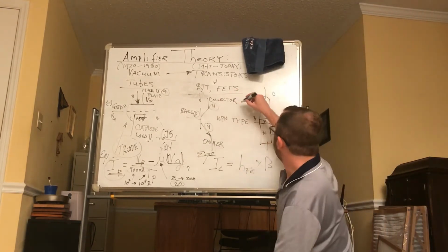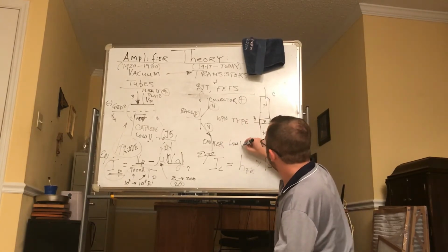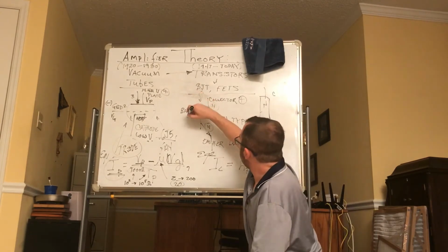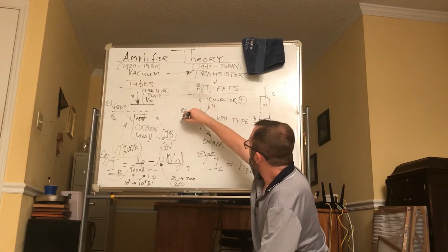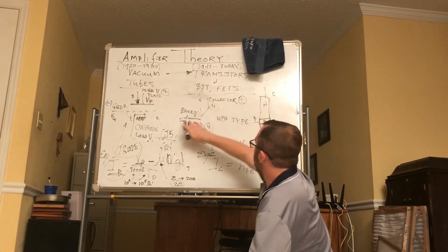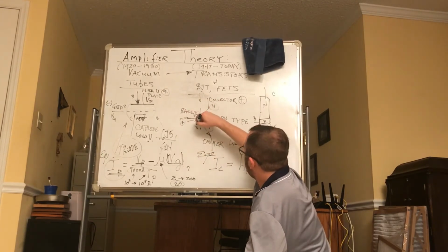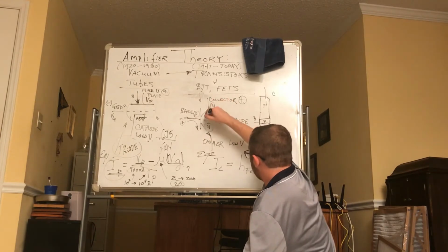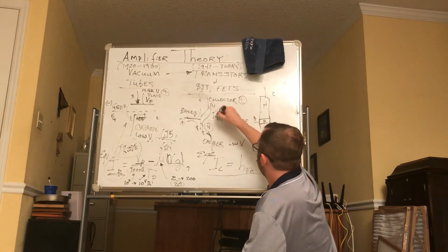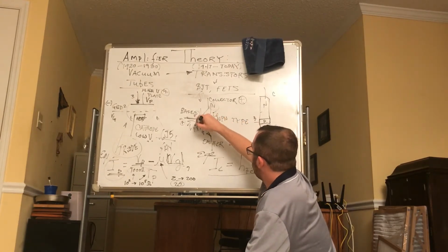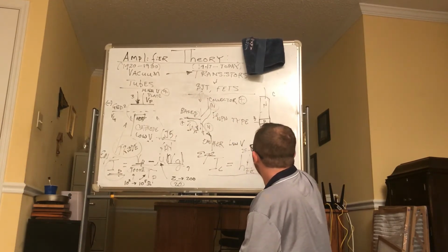The collector, similar to the tube, is at a plus potential. This is at a more low voltage. And this here, on the base, would be at a plus voltage, although not as large as this one. If there's no voltage here, then no current flows. If there is a voltage here, and therefore a current flowing, then the larger current flows. But the control equation is that the collector current, which runs from collector to emitter, is controlled by the base current here. And in practice, beta is between 25 and 400.